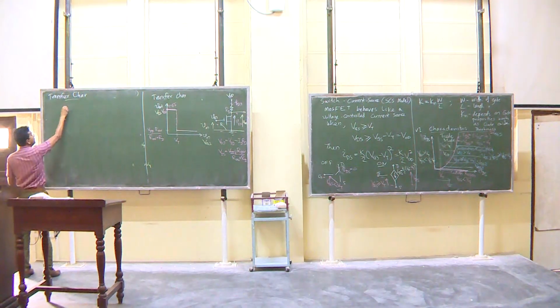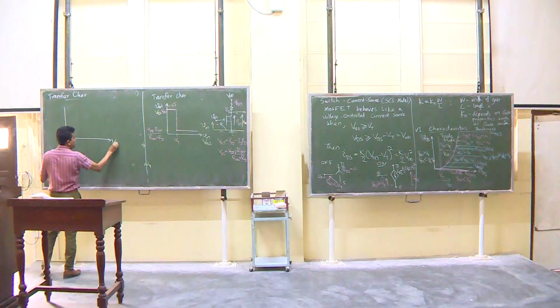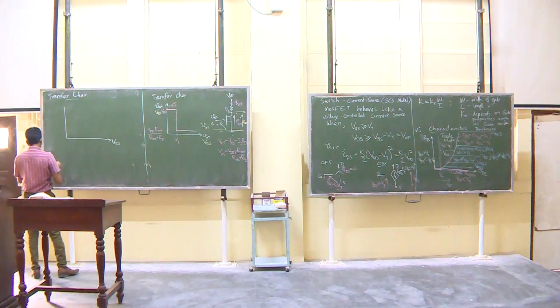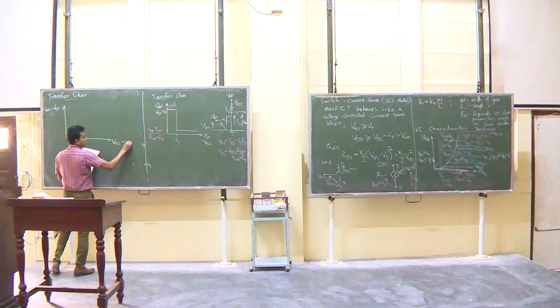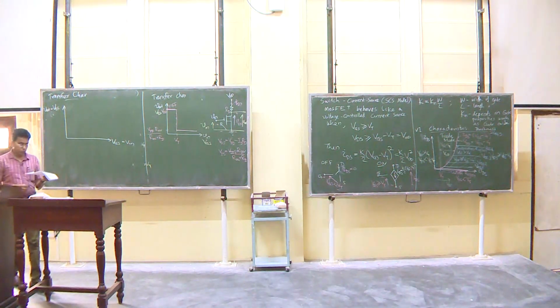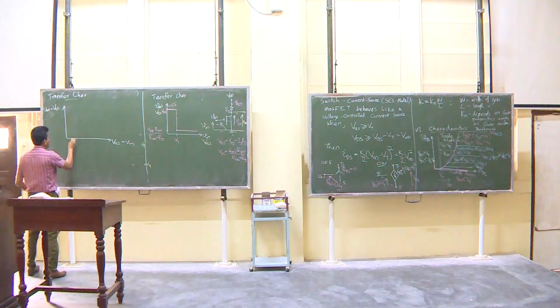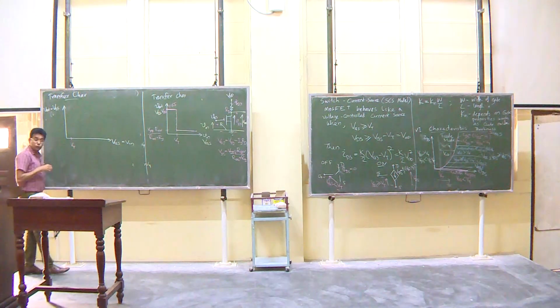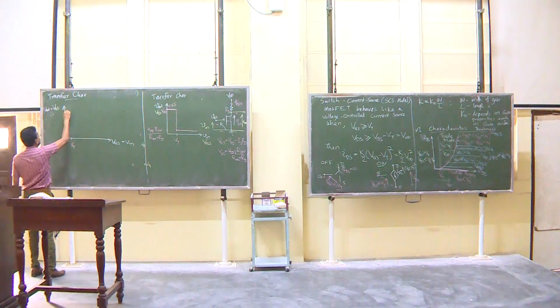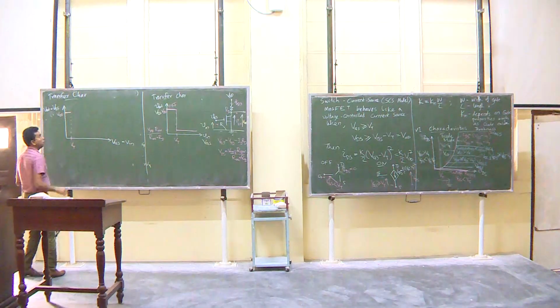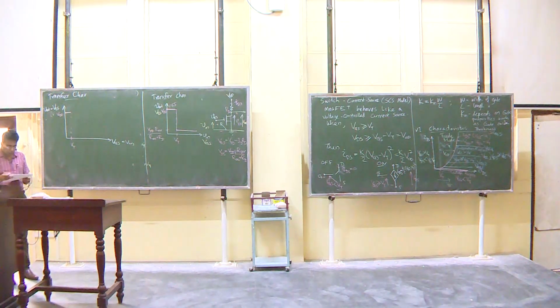So, in transfer characteristics, what you have is VGS, the input, and the output VDS, V out. So, that is my input output characteristics. We know up to Vt, up to threshold voltage, this is cutoff, nothing has changed. So, therefore, output is VDD, that has not changed. That has to be like that. And what happens after that is what we are interested in.